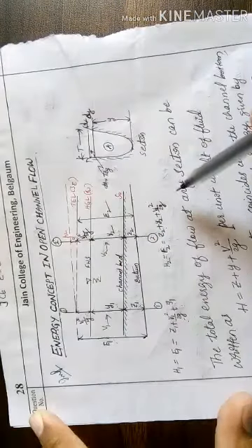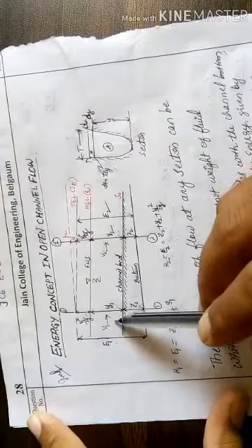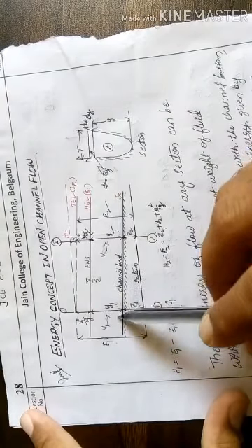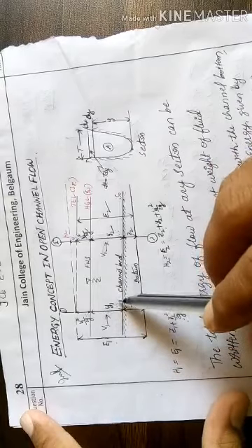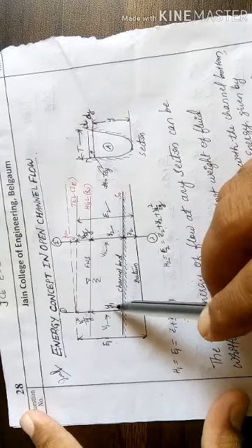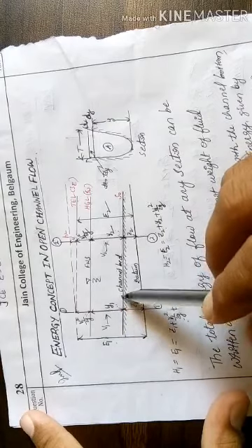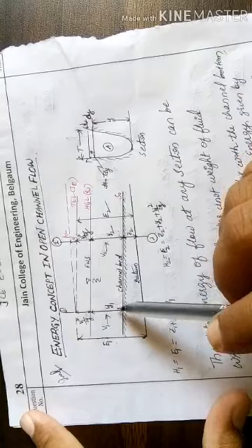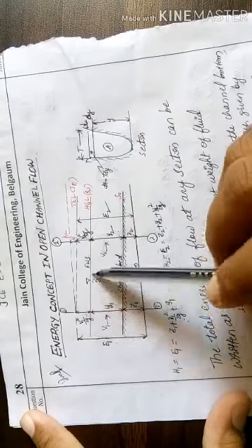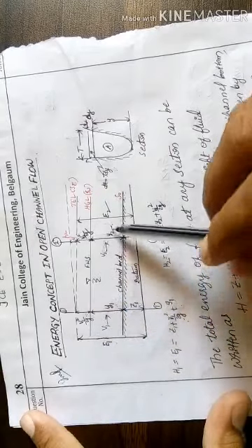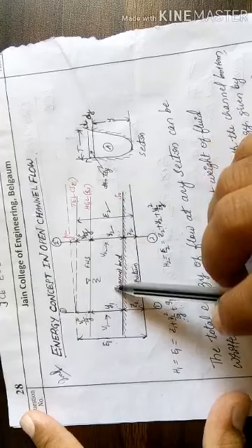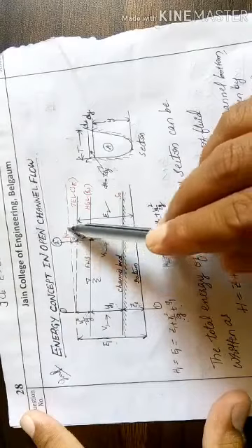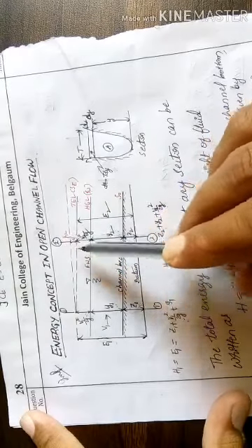As we know, whenever the fluid is in motion, it experiences certain resistance. That resistance is because of the friction in the fluid, as well as the friction between the surface of the channel and the fluid. Hence losses occur. So along the direction of flow, the energy decreases because of the losses in the fluid. That loss can be represented as HL.